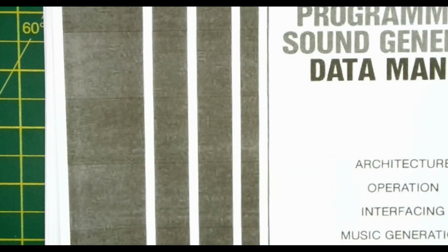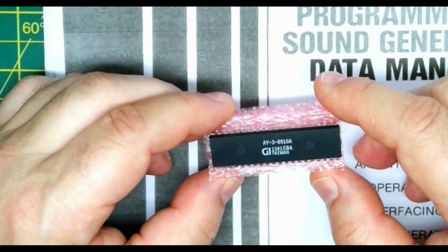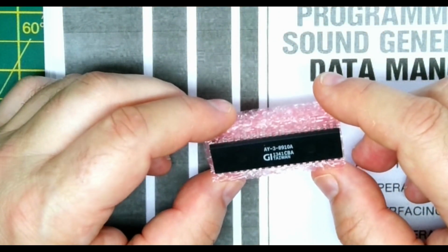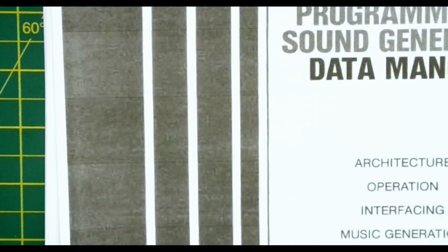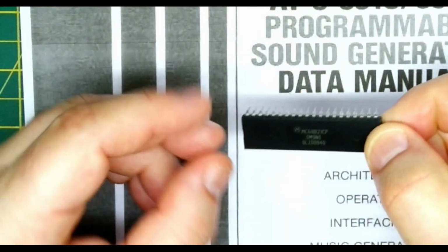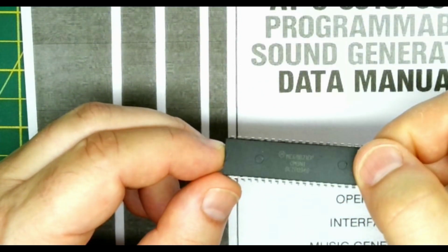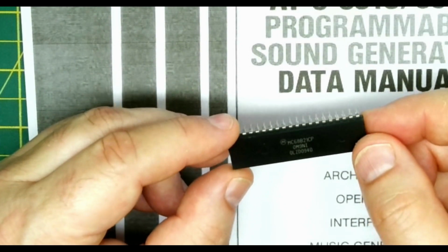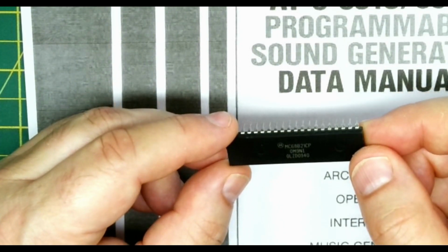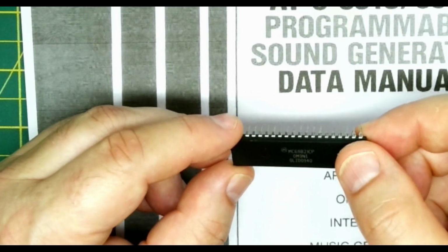So what I've got here is the General Instruments AY-3-8910. So hopefully this is a genuine part and works. The peripheral interface adapter, because in one of the next videos I'm going to upgrade the clock in the Nanocomp to be twice the speed, is actually a 68B21 chip. This means it's capable of running with the 8 megahertz clock.